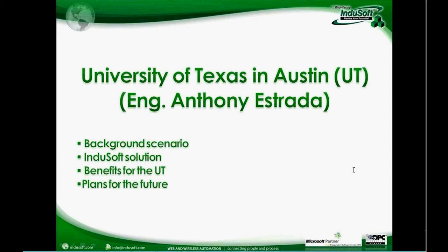There is one question here, what PLC I recommend for building automation? That's a hard one to answer because different projects have different needs. Depending on the market, for instance, in detention, we have worked a lot with Allen-Bradley PLCs. They are pretty much the standard for that industry. In other industries, we have worked a lot with Beckhoff PLCs as well.